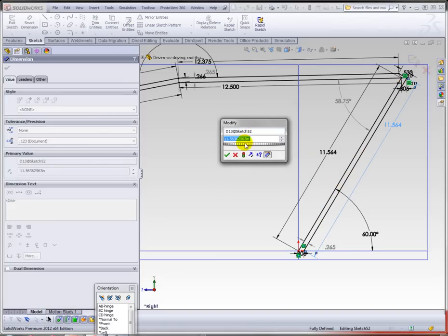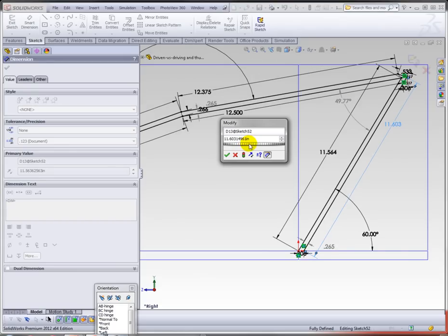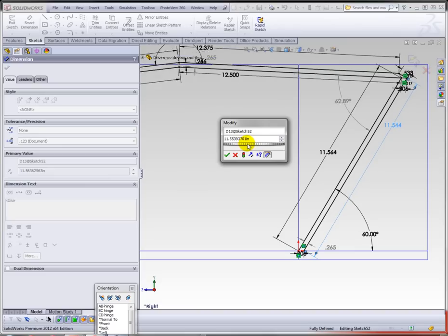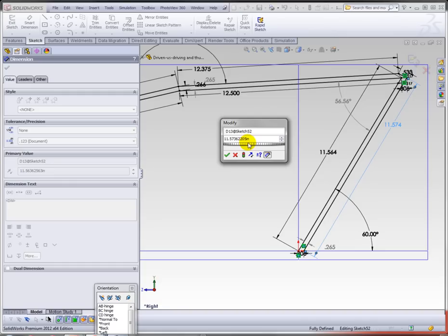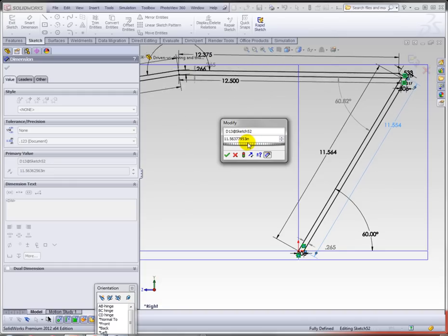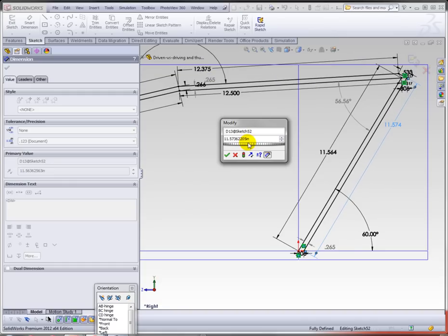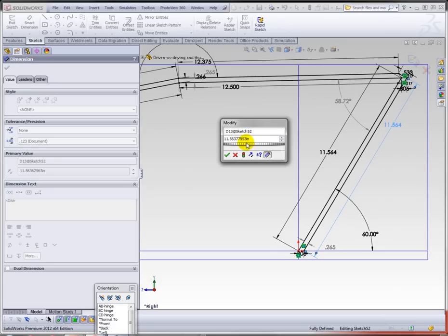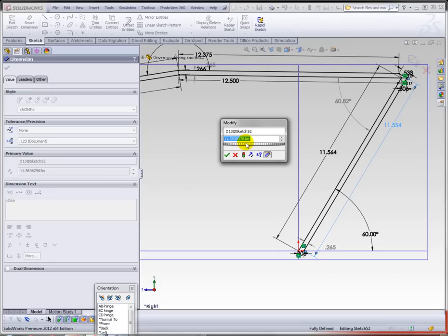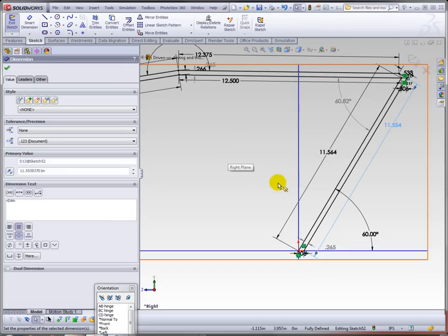velocity of the wheel. So if I hold down my Alt key while I scroll the wheel, I actually can get 1/4 the spin value that's set in my system options, and that's what I'm doing right here, is that I'm actually just holding down my Alt key while I spin the dial, and thereby I can get a finer increment for my thumbwheel. Now, holding down the Control key will give me, I think, 4 times that value.